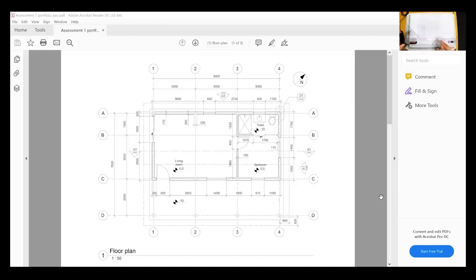So all the objects that are closer to the cut plane are shown with darker lines because they are closer to our eyes, right? And this is a horizontal cut plane seen from above, like a bird view. So the objects that are close to us are darker, and the objects that are more distant from us, we use thinner or lighter lines.